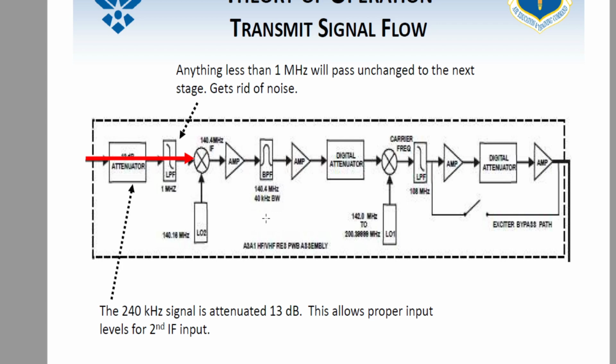Yeah, you remember talking about that heterodyning thing in the beginning of the block? Right? You combine the sum, the difference, the two original frequencies, and the carrier, and you get the output. So that's what we're doing here. We're doing mixing. Now we're going to add something in here as well, this local oscillator frequency. We're going to add local oscillator frequency 2. It's a 140.16 megahertz local oscillator frequency, and this is a 140.4 megahertz IF. That's what's coming out. So don't confuse these two.